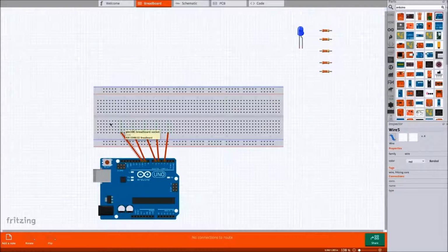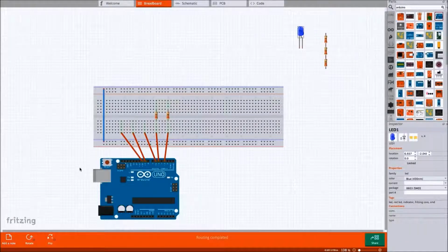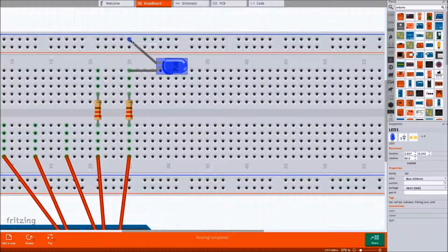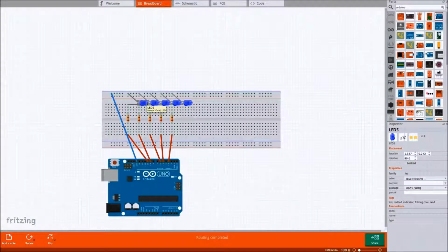Now, you will need to complete the circuit with a grounding wire, and it's grounded. See how these green lights are here? Because it flows from the Arduino Uno through the wire, through this, into the resistor, and the resistor makes it continue here. So, in order to continue the circuit, you would need to put the LED around here, the shorter end here, and the longer end here. These green lights are now all along this negative row right here. Put this wire here into ground, to ground this circuit. So that's the completed circuit there, positive flowing in parallel. Each wire is in parallel to each other, so these resistors and LEDs are all in parallel.